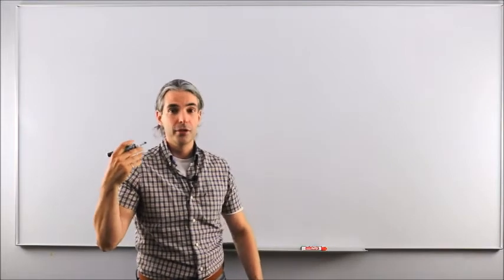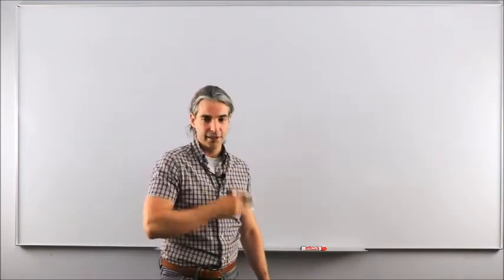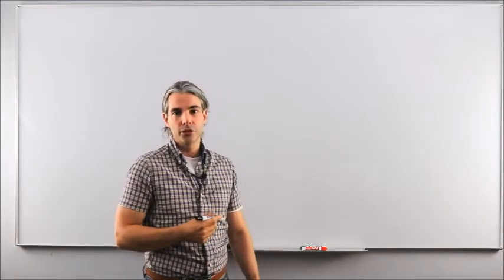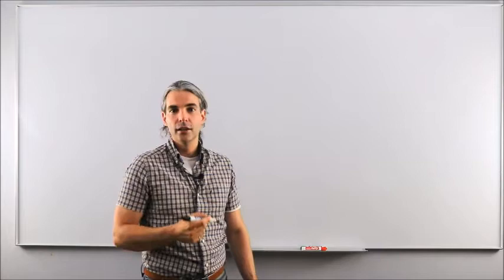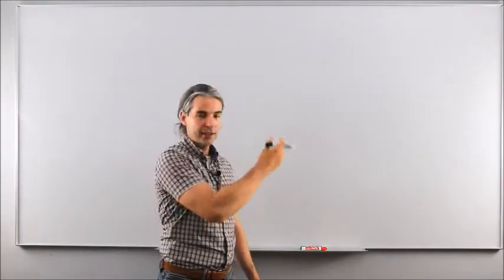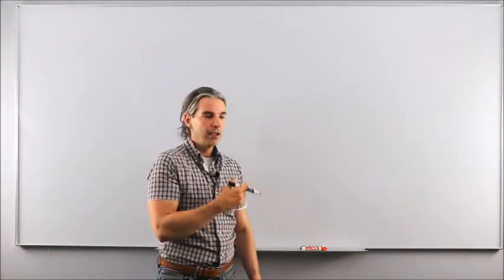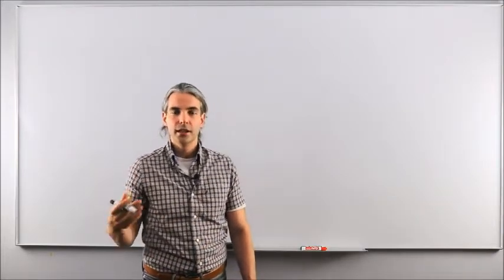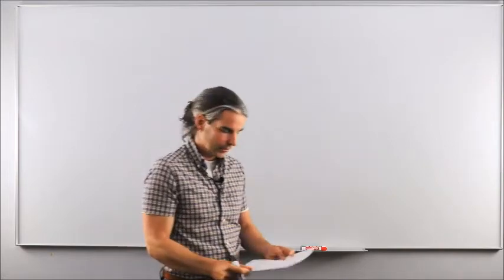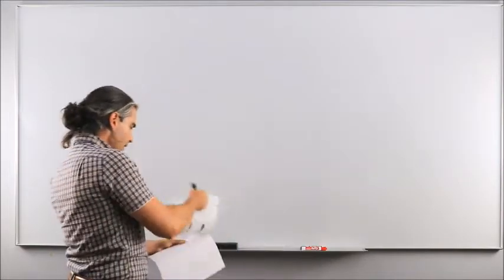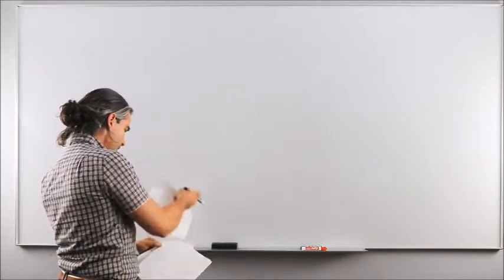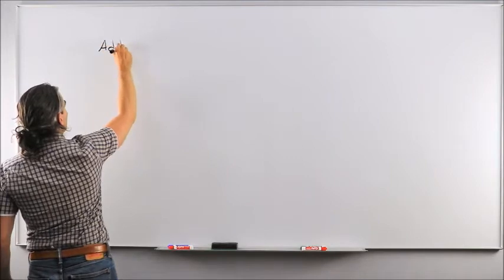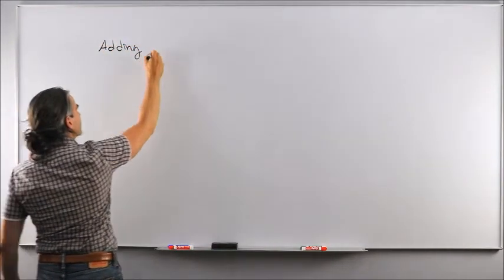But before we can even think about doing that, we need to step back a second and think about what would be the effect, now that we know how to construct a root locus, what would be the effect of adding a pole? How would that affect stability? How would that bend the branches? How would that affect the number of asymptotes? And similarly, we're going to do the same thought process about adding zeros to the root locus, okay? So let's first talk about adding poles to the root locus. What would it do to an existing root locus?